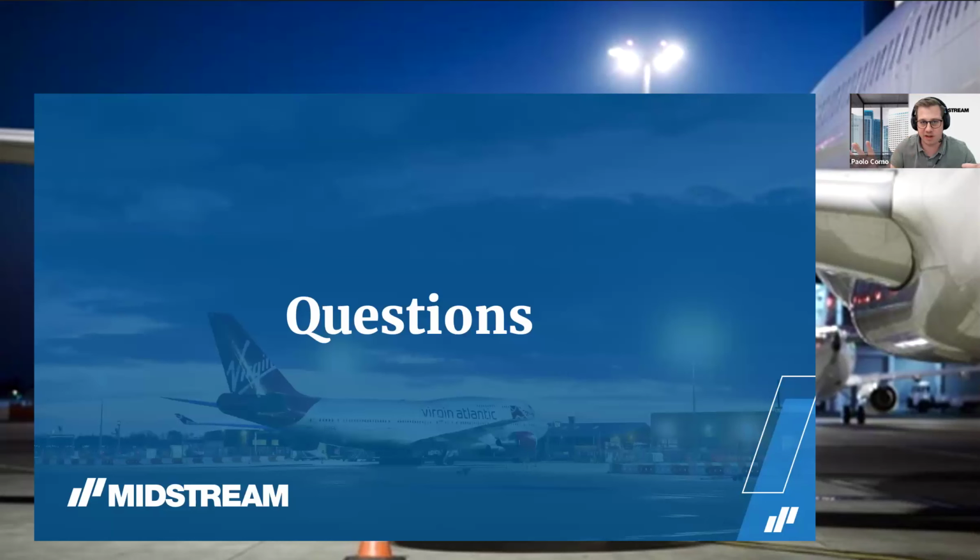But that's extremely difficult to happen on actual aircraft stands, but they always have to be evaluated individually. You cannot group them together, because you will have instances when you group 5 of them together, and you have, oh, I have a great lux level and great uniformity. But in reality, the central 2 or 3 would be a 10 lux average by themselves. So meaning when you actually operate that aircraft that's parked there, you want to have as good visibility of the rest. So always evaluate them individually.